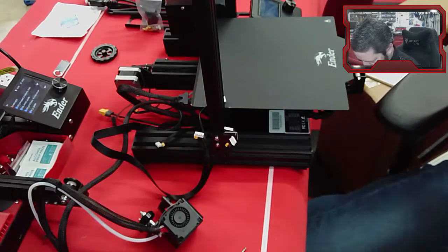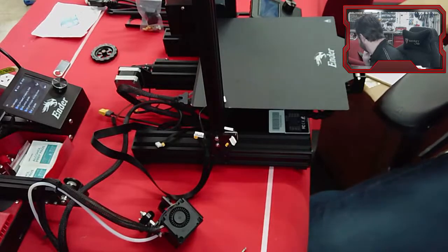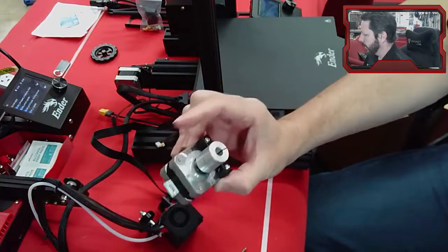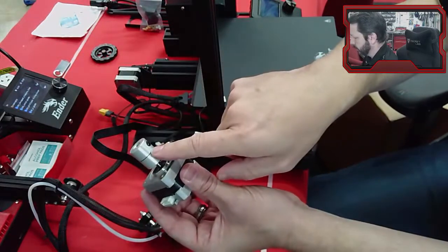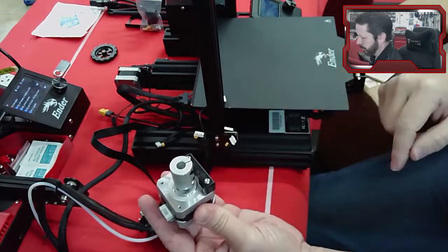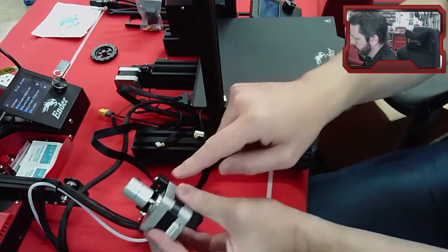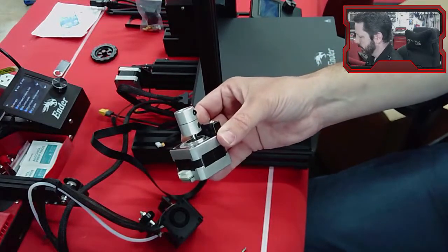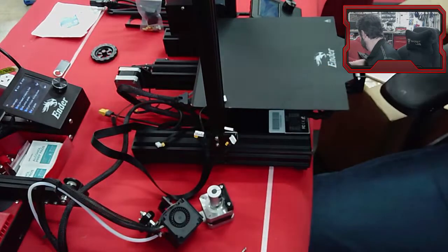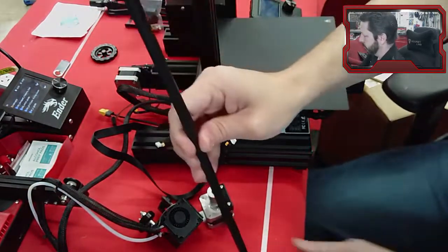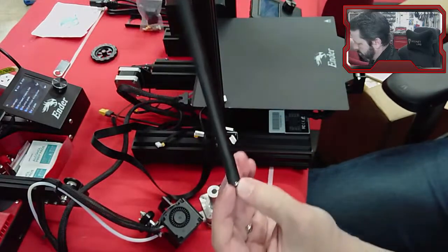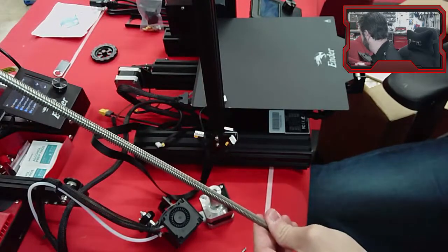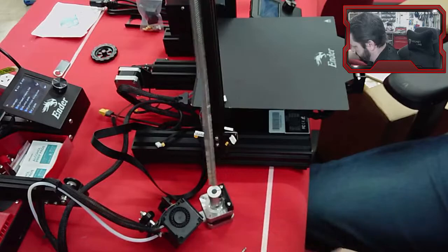All right, now it wants the Z motor. That's this guy. So it's the one with the coupler on it. Now in this coupler, these split couplers like this, if yours isn't already installed, there's a large size and the other one is a small size, because the Z motor doesn't have a shaft the size of the Z rod. So this is a lead screw that we need to get out of here. Hopefully it's straight.